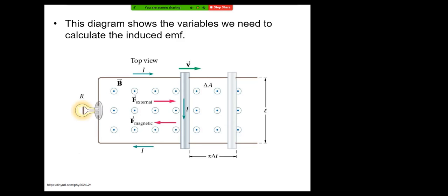So you basically move this in that direction, and because of that, you are changing the magnetic flux, so then you'll have induced EMF over there. So basically, you probably will pull this, okay? That means there's mechanical work being done, or mechanical energy is actually converted to electrical energy over here, provided to the LiPo, right? So that's one type of electric generator you can design.